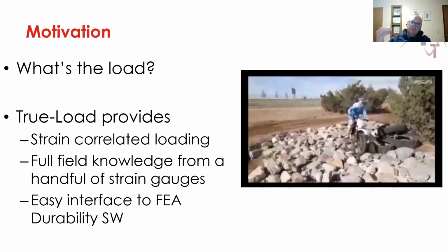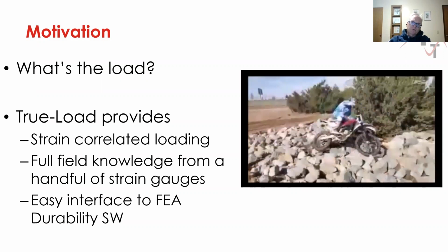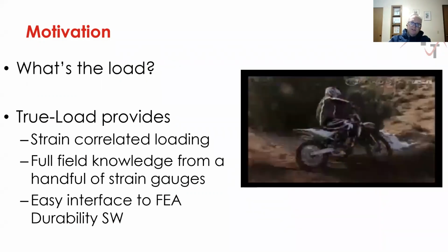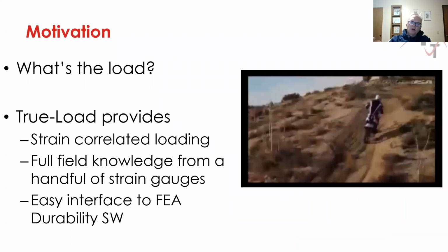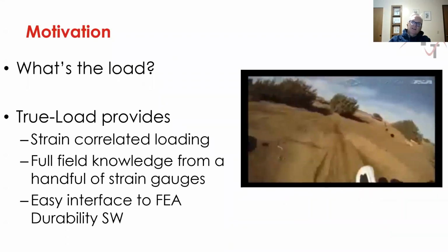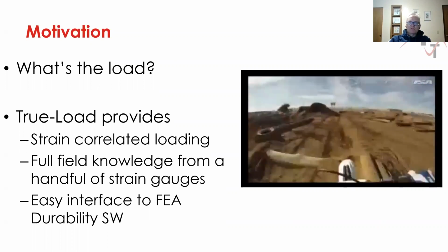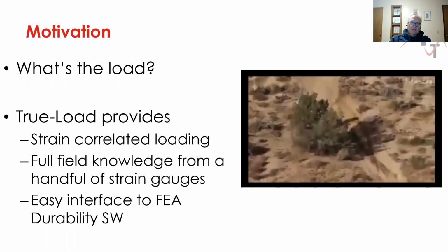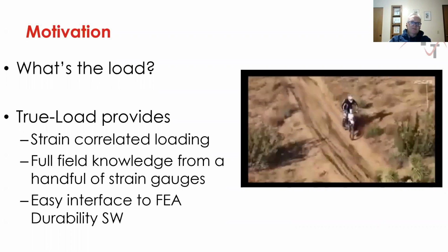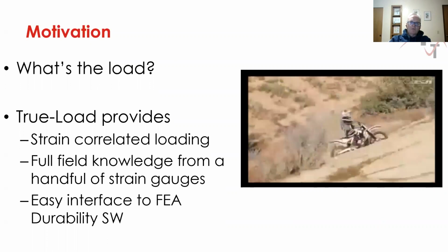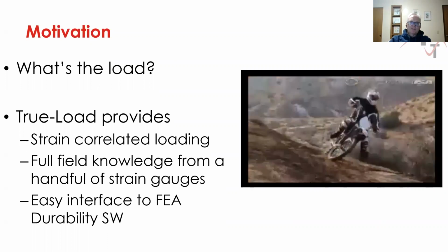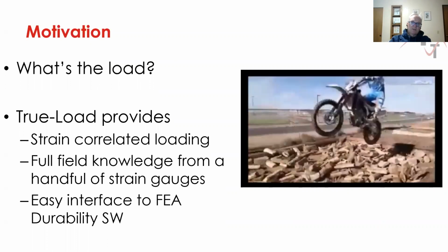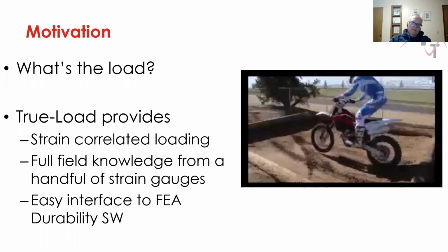So we're going to put strain gauges on the swing arm, the crankcase, the frame, the handlebars, the fuel system, the luggage system, the fenders. We'll put strain gauges in all of the subsystems of this motorcycle, but the subsystems become their own load transducers. And then we'll get operating loads for these subsystems to use for design and optimization, okay? So this is a really great and powerful tool and allows us to fully understand all the loading on this motorcycle. Even though the loading is very nonlinear, the response to the components is linear.